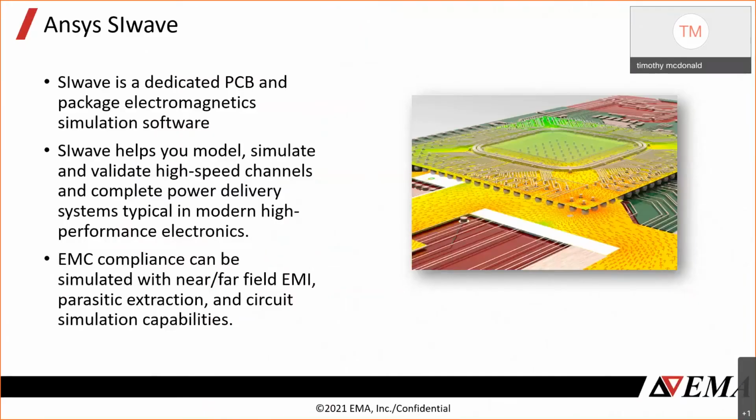So the first part of this, we're going to talk about modeling the PCB itself in ANSYS SIwave. SIwave is a dedicated PCB electromagnetic solver that is really purpose-built for PCB and package modeling, and it lets us model, simulate, and validate both high-speed data channels as well as the power in the PCB, typical of modern electronics, and we can model the near-field, far-field EMI in this case when we're using SIwave.